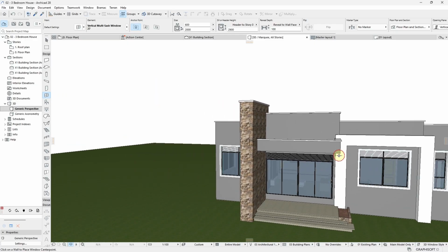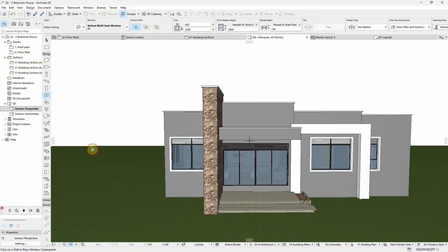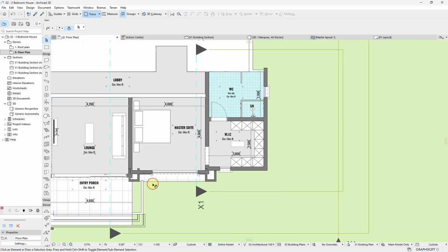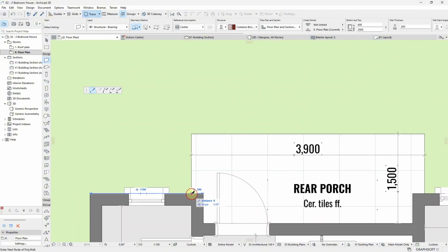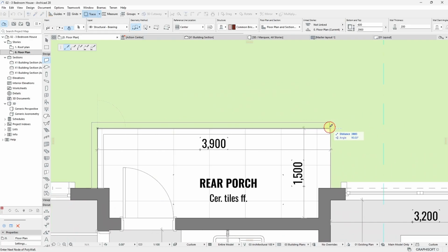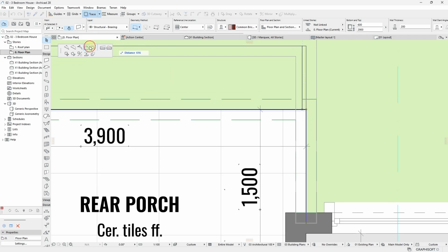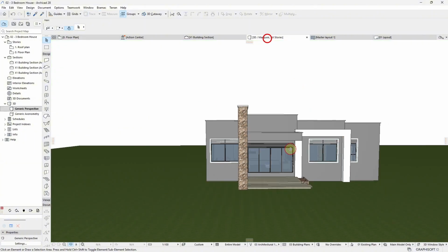And now, finally, let's assign different colors to the different parts of the building. So I would like this part here to have its own color. This one to be. Oh, before I forget, we have to do a balcony at the back. Yeah, here we have a balcony like this. I'm going to offset this inwards by 200 because this is a beam passing exactly at that rear balcony.